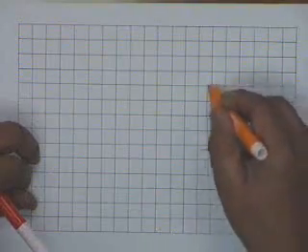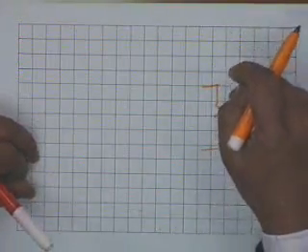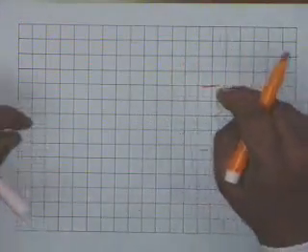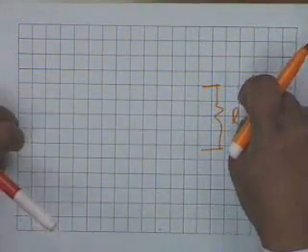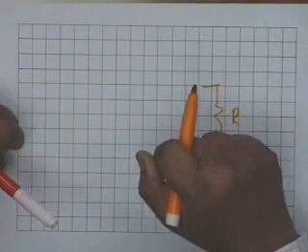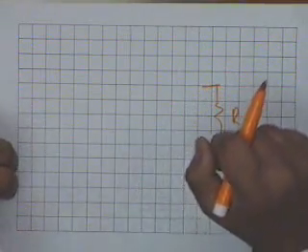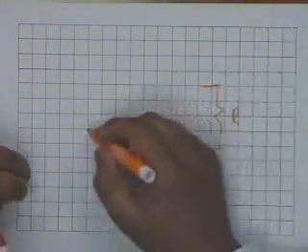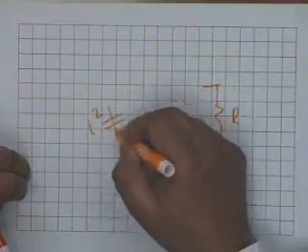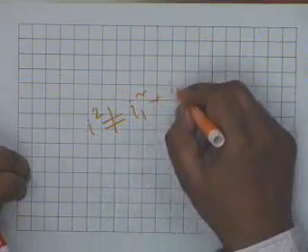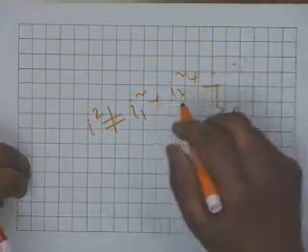That is, I have an element, let's say R, and I wish to find out the power consumed by R. I find the power due to one source acting independently. Why not? Because I squared is not equal to I1 squared plus I2 squared and so on.